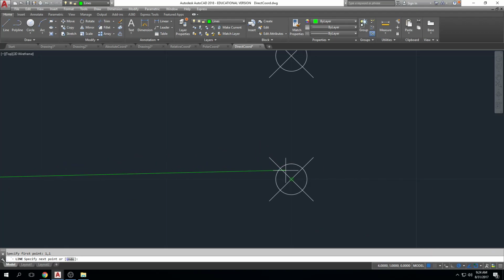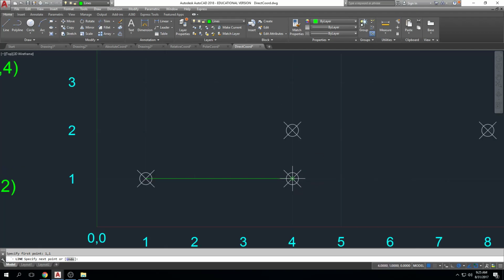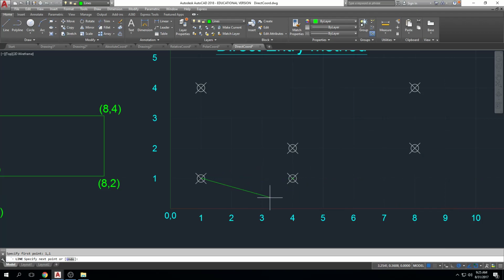Okay, come back over to AutoCAD. Do you see how that node snapped right to the center of that? So a couple of ways I can get straight lines. Make sure my node object snap is turned on, right? Or just turn my ortho on, F8. Okay, it's turned off right now. You see that? F8, and it turns on.